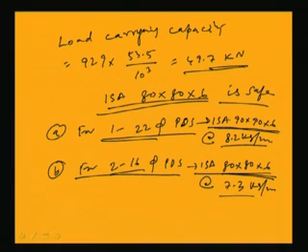We had to go for ISA 90 by 90 by 6, whereas if we use 2 number of rivets with a lesser diameter, then we will see that the 80 by 80 by 6 section is quite okay.